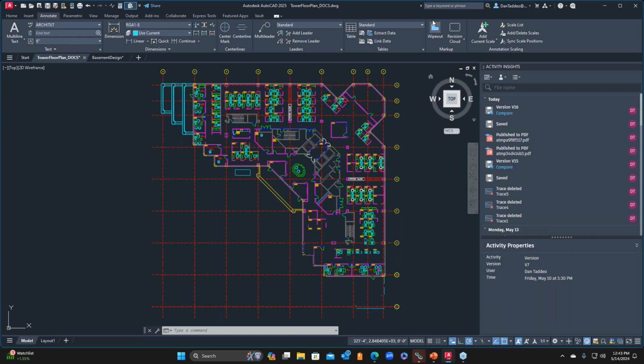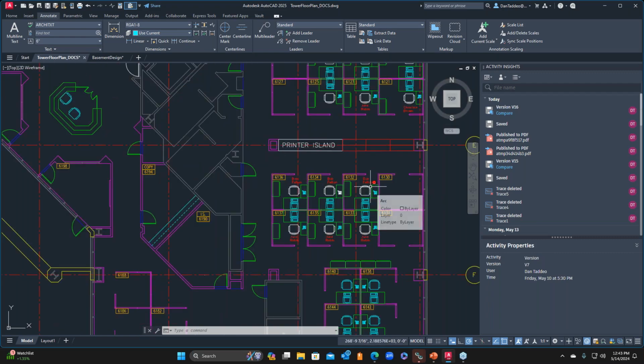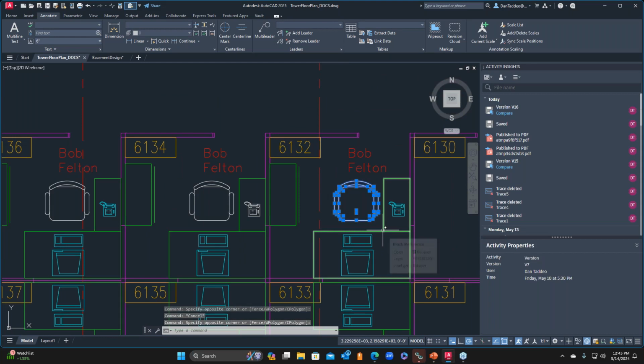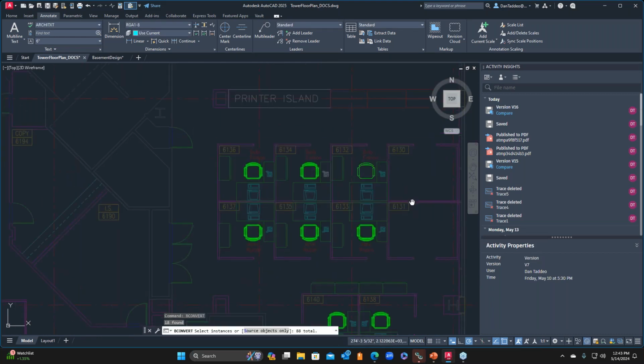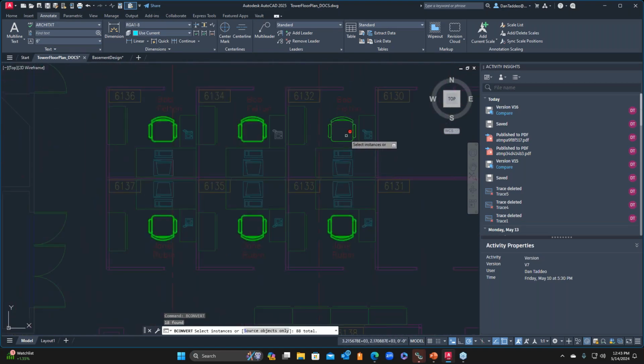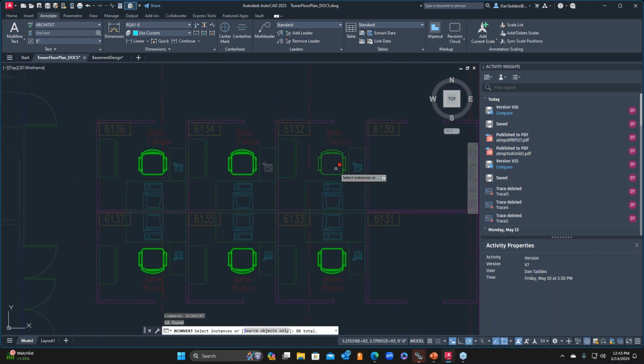So it looks like we have some questions, though Gary has answered a lot of them. Thank you. Can you do a batch convert on all files? Well, it allows you to. So the BCONVERT tool, right? If I have this chair right here and I select one instance of it and use the BCONVERT, what it allows you to do is, based on what it has selected, see, it has selected a lot of these, convert these into a block, but it looks for similarities of other things.